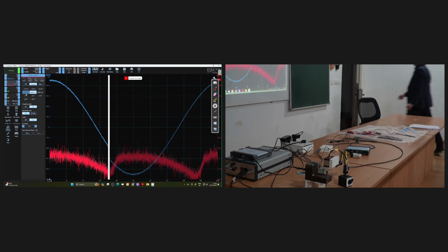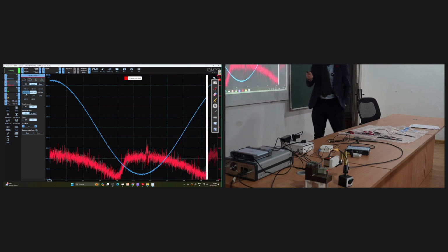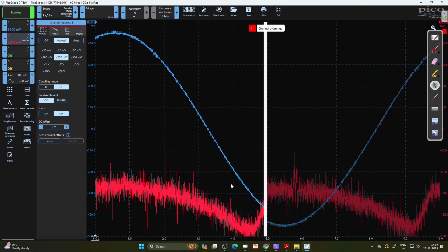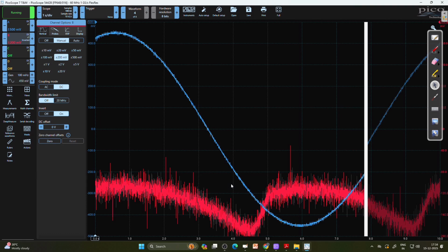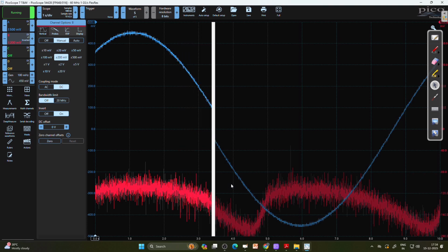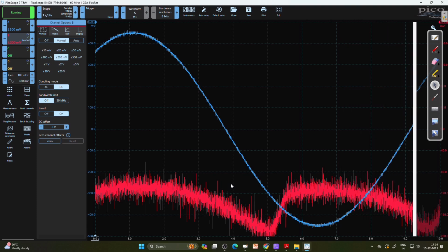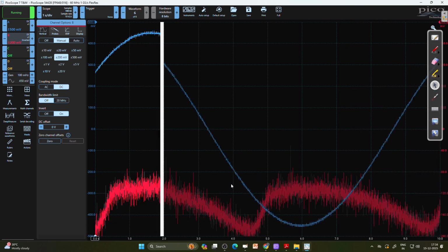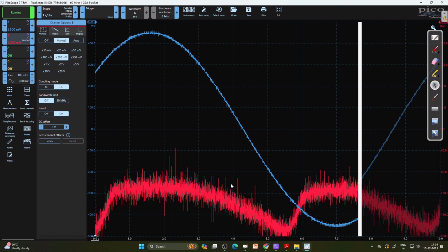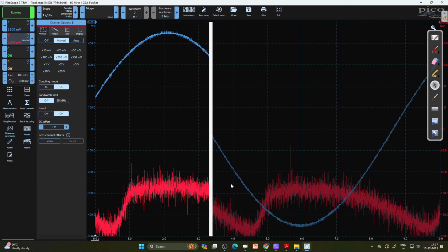And now what you can see, first of all, is that always when we pass 0, shortly after, like here, before we reach the maximum of the blue curve, the polarization changes. So the elongation becomes maximum, and then it changes. And then again, here we go above 0, and shortly after above 0, the elongation abruptly changes. So this is when we reach coercive field strength and when it shifts around.